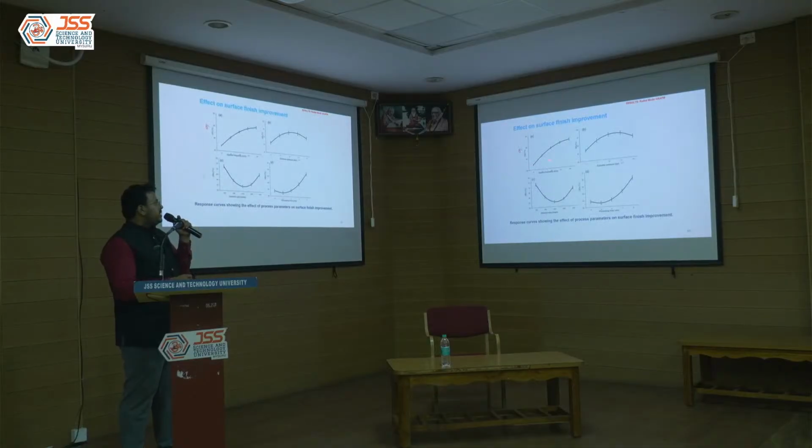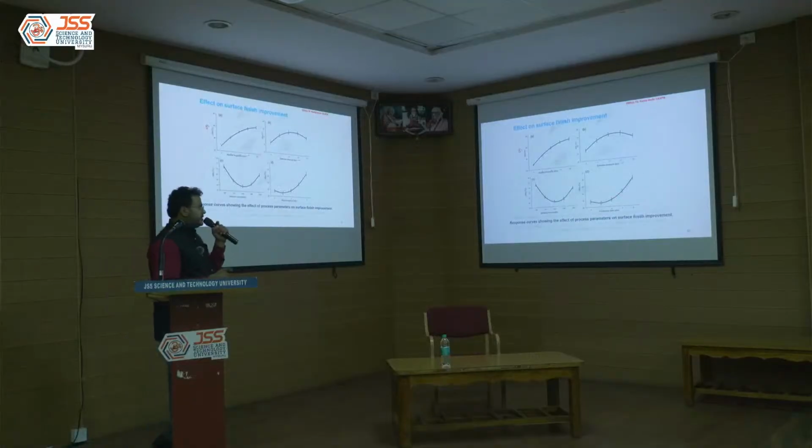When we observe the individual trend, like applied frequency, extrusion pressure, abrasive size, and processing time on the response 1, that is delta RA, we observe that there is an increasing trend in applied frequency, extrusion pressure, whereas a decreasing trend and then further increasing in abrasive size, and processing time, there is an increasing trend, etc.